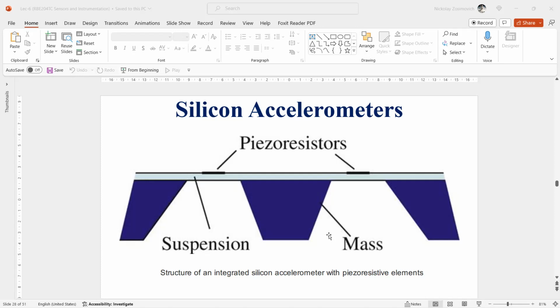Instead of integrated piezoresistors, electrodes are deposited at proper places in the structure, forming flat plate capacitors. The mass moves due to an inertial force, resulting in a change in distance between the plates, and this causes the capacitance to change. By a special configuration with 3 or even 4 masses and associated electrodes, it is possible to realize a 3D accelerometer in a single piece of silicon. Together with the MEMS sensor, additional electronics and signal processing, for instance voltage regulators or an ASIC, application-specific integrated circuit, and a temperature sensor for offset compensation, all of that can be housed in a small package.